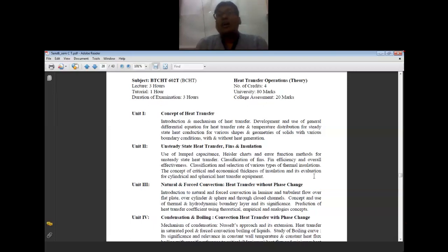So similarly, in case of your furnaces, direct radiation zone and the convection zones are there. In a furnace convection zone, the tubes are studded. So that is the purpose of providing the studs or providing the fins, so that you are extending the surfaces so that the heat transfer will be at a faster rate.